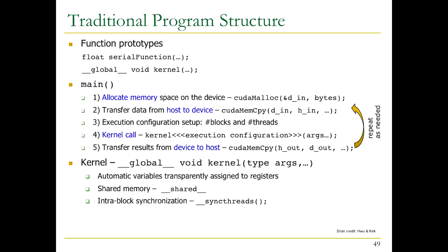That's the coarse-grain synchronization. If at some point you need to synchronize this thread block with this other thread block, you need to wait until the kernel terminates and then launch a new kernel.